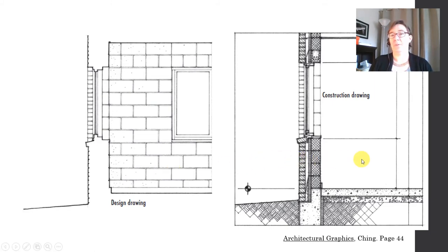In the construction drawing, you still have thick profiles. They're much more detailed profiles because we're now showing more detail about how the wall is built. And then you've got a thinner hatch pattern for those cut materials. And then a very light line for some items that are beyond the cut line. We're using a kind of medium line here for dimension lines.